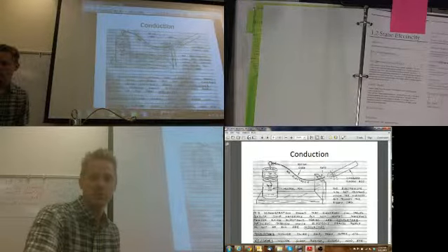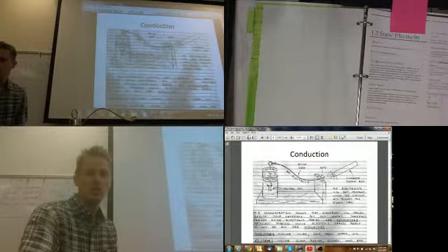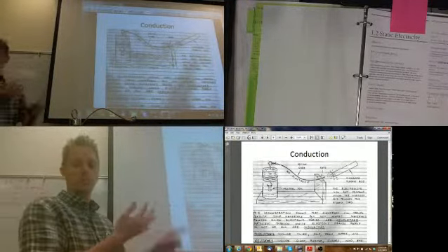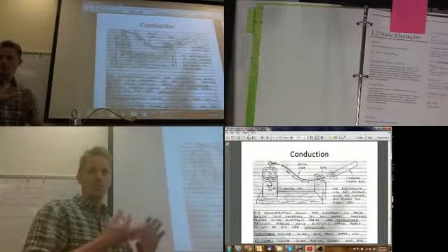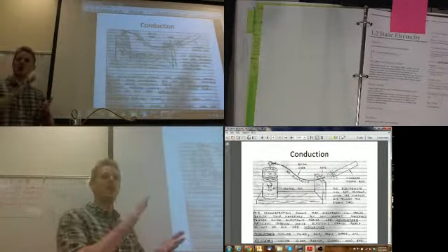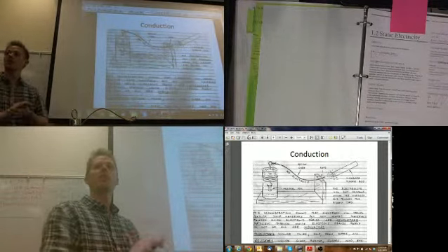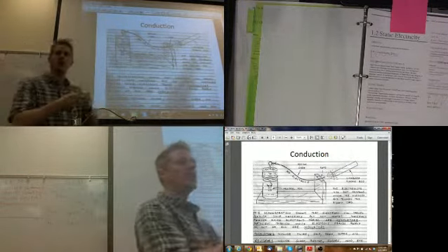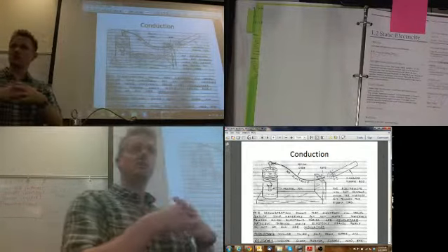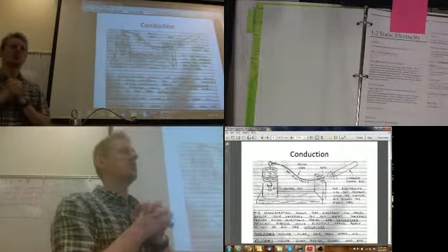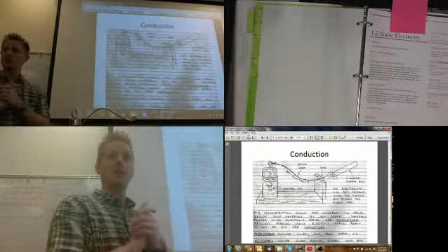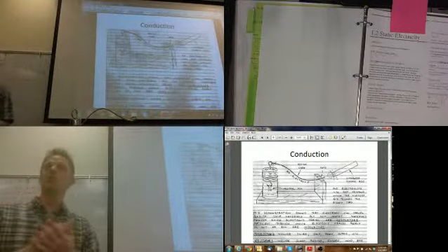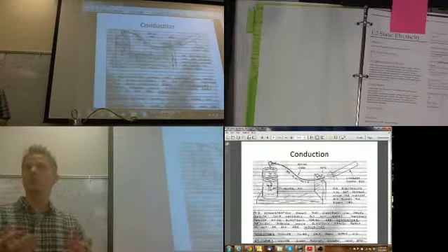Conductors would include silver, gold, iron, copper, etc. What's the best conductor? Gold, silver, or copper? No, silver is the better conductor. What material has the least contact resistance? When two things are pressed together, like sockets and things like that, that's contact resistance. What has the least amount of contact resistance? Gold. That's why things are gold plated, not because gold has the least conductance. If you look it up on a chart, silver is a better conductor. Silver is more expensive, so we use copper.